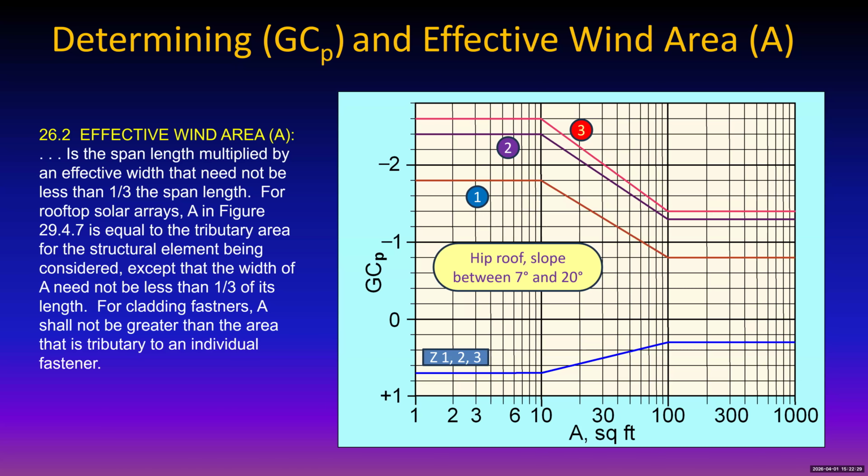We put in some rails and we put in some attachment points. Lots of good commercial stuff out there. You just talk to your suppliers and they'll tell you what they've got available. And the manufacturers have lots of good data sheets to go along with their rails. The rails are designed to last 25, 30, 40 years. A typical mounting clamp can hold at least 800 pounds and maybe more, although some of the standing seam metal clamps are 500 pounds or less for a single point pull.